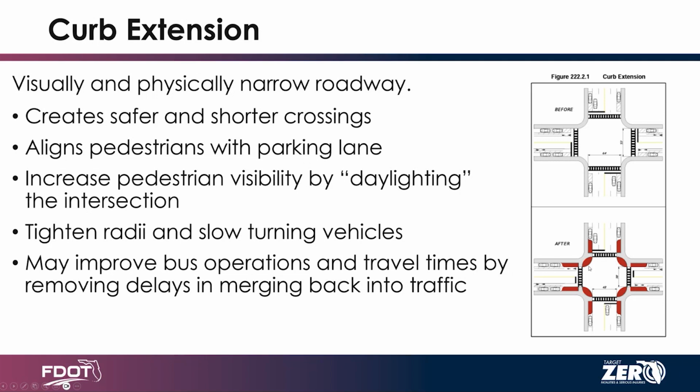Installing the curb extension better aligns the driver turning movement. Instead of making a higher speed, potentially fast turn, they cut the curb radii. They make a slower turn, more likely to be able to see pedestrians and cyclists at the intersection as well. And potentially there could be some operational benefits, both to bus operations and even to reducing pedestrian flashing don't walk times.